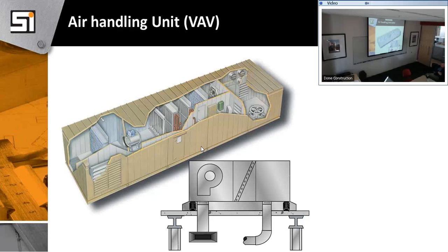Okay, good. Is the air you're bringing out on an economizer the same thing as makeup air? No, good question. Makeup air is, on a 90-degree day, I have to give you guys fresh air, I can't just keep recirculating it. The theory is if I recirculate, I'm not spending as much energy because I'm not putting in 90-degree air, but we have to ventilate. The nice thing about California is there are codes, ASHRAE, for minimum fresh air for spaces, based on square footage or occupancy, like this room right here.